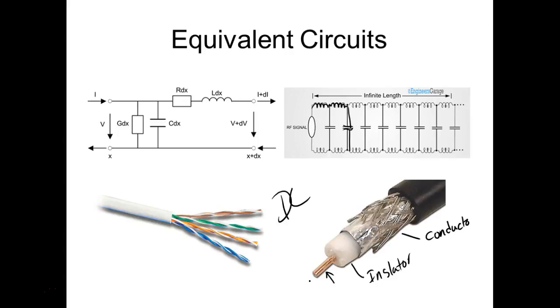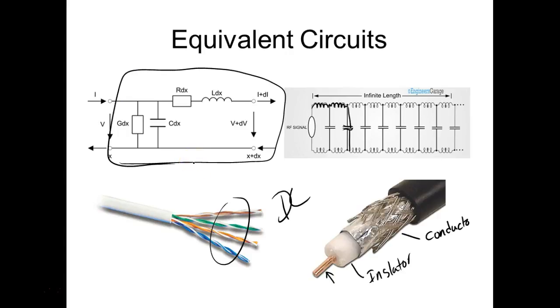This is something called twisted pair, which we use in networking, and this is the equivalent circuit of a twisted pair cable. It also has the same characteristics. But I think to get that on twisted pair, the minimum length of the cable has got to be at least 4 feet. Above that, it doesn't change. If I have a 75 ohm coax cable, and my transmitter has a 75 ohm output, and my receiver has a 75 ohm input, then everything in the system matches, and now my cable company can transmit maximum power between the transmitter and the receiver.